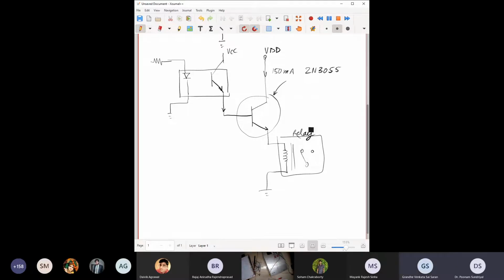Okay. So here we are simply using the transistor as an amplifier, right? No, we have not used it as an amplifier. We have done the following. We have used a photocoupler to drive the base. When the Arduino signal is high, this LED will shine onto this hidden base. This is not exposed to you. When this is exposed, this switches on with some nominal voltage drop across the collector emitter. So you essentially drive the base of a larger transistor via this resistor.